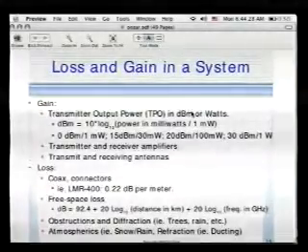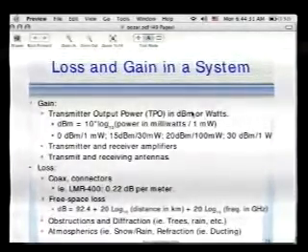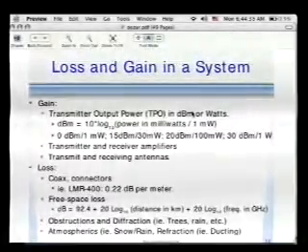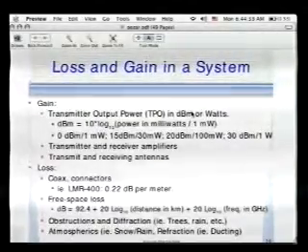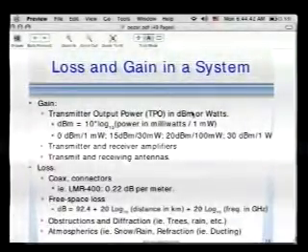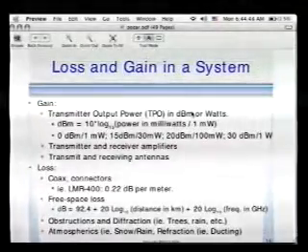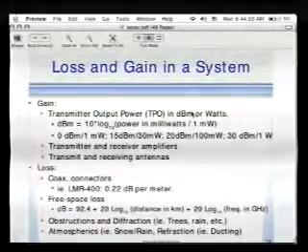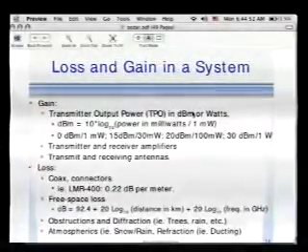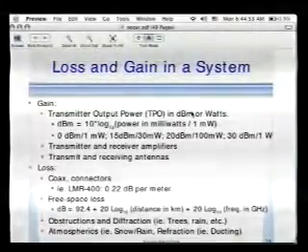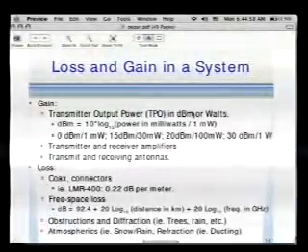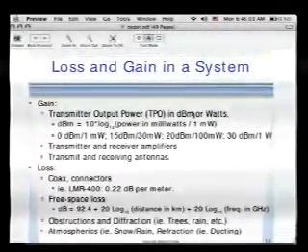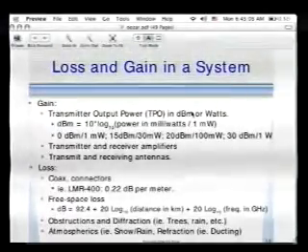and you also have gain effectively in the transmitter output. You're going to have loss in things like coax, connectors, what's actually called free space loss, which is the loss between one antenna and the other antenna, which ends up being at least 96 dB, and then whatever mileage that you're going to have between those two. You're also going to have obstructions that will cause diffraction, which will cause attenuation as well. And then atmospherics. In other words, how much rain do you have? How much snow? At 2.4, it doesn't really become a factor, but if you're starting to use like the 60 gigahertz band, you're going to have a problem.